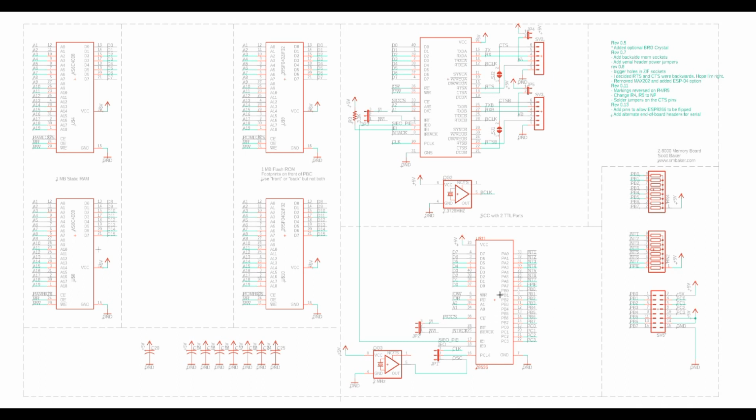It's actually the 8536 CIO, which is counter, timer, and I/O. At this time, I'm not using the counter timer feature, but I am using the I/O, and I'm using it to implement an interrupt controller. So, a total of 7 interrupts come in from the H8 bus, and those will go in here, and they will generate, down in here someplace, right there on this INT line. When one of these interrupt bits changes, we will throw an interrupt out here through the non-vectored interrupt.